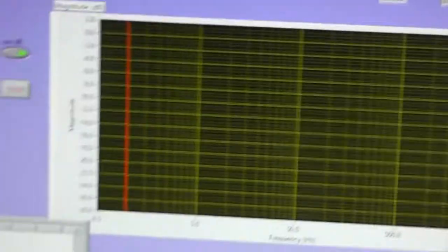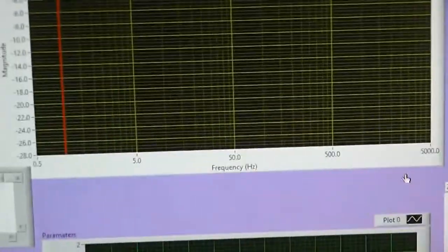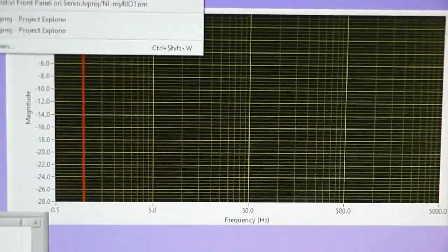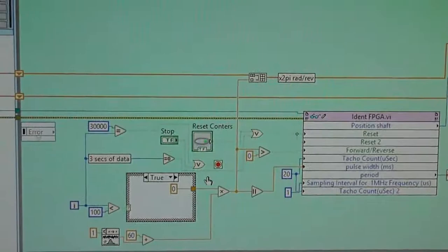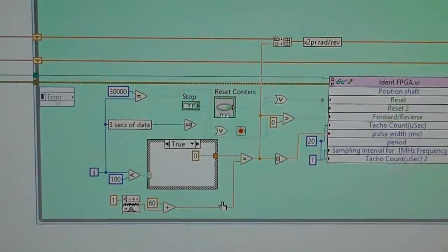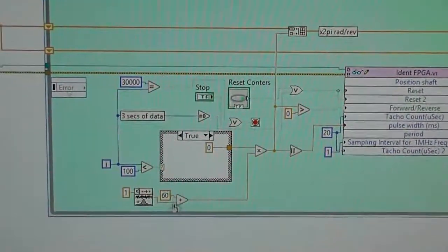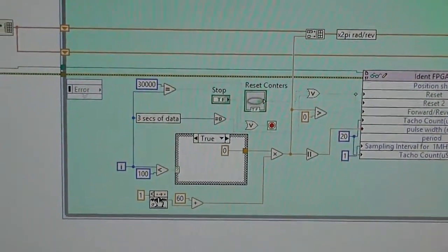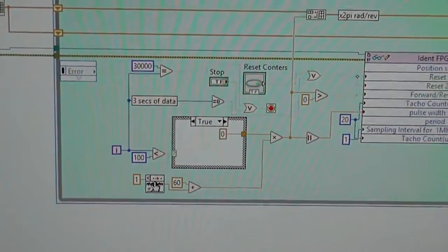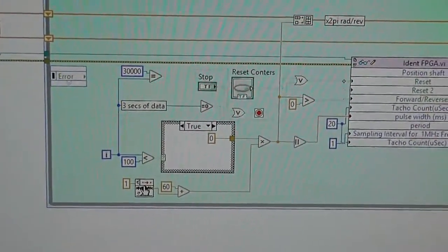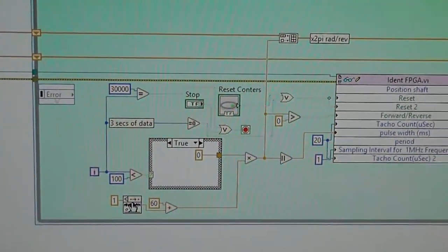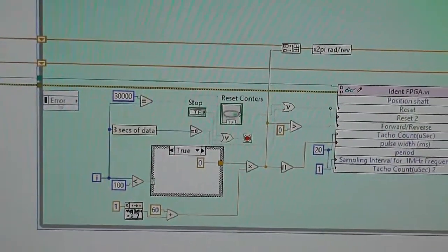Here it is. So I've written a program, and what it does is it reads the data. Now, what data? Well, what I have to do is get the motor running, which I do, and I add white noise into it. The thing about recursive-least-squares is it doesn't work if you just put constant values in. It needs what's called persistently exciting signals.